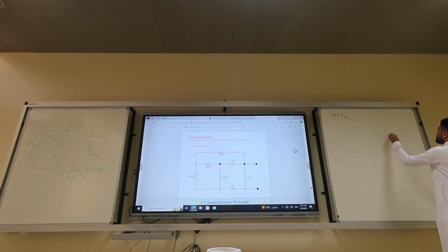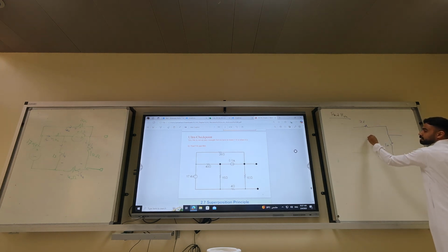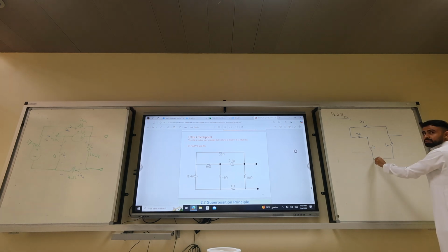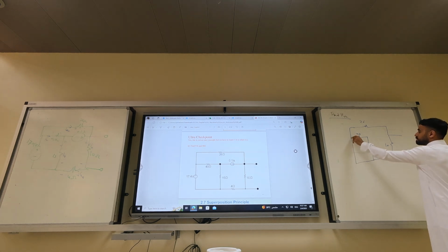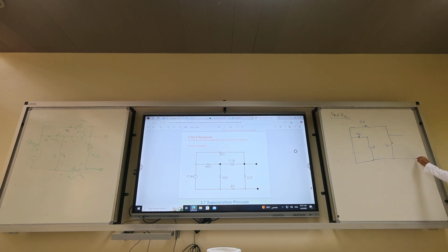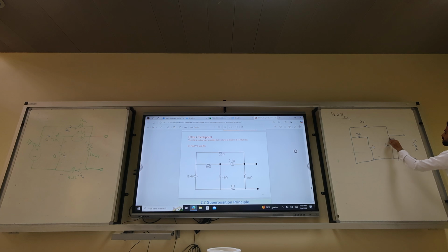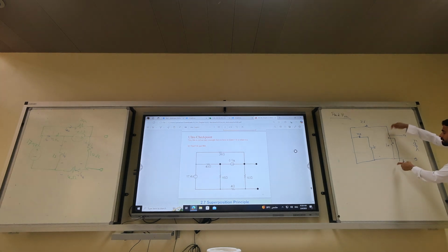What is Thevenin? Thevenin, redraw the circuit. That's a 10. Open the current source. That's a 26. That is the 15. That is the 40. You short circuit the voltage source, right? And you look at your Thevenin. Thevenin would apply an ohm meter here, which is like applying it there. The key here is applying it here. We have resistance. Oh, the 4 ohm.